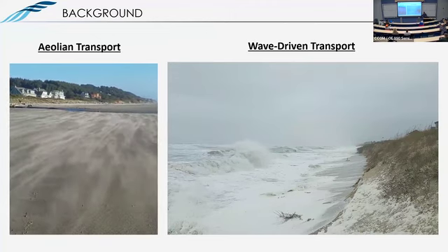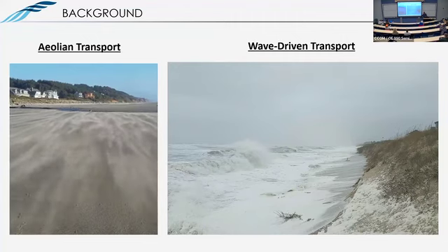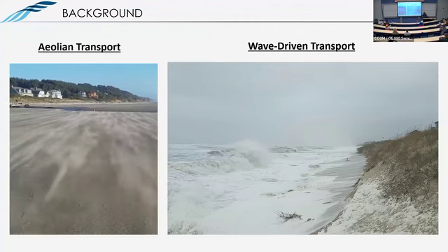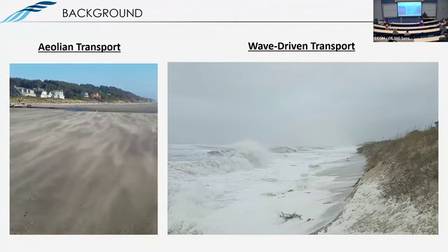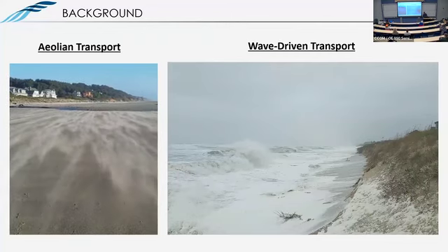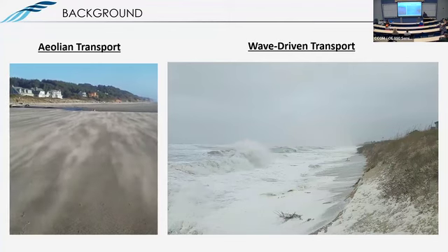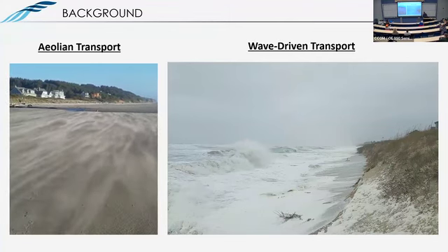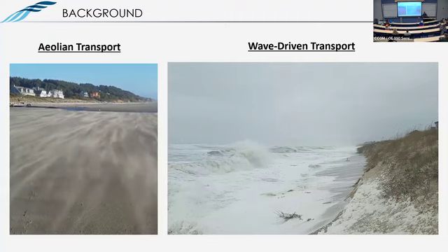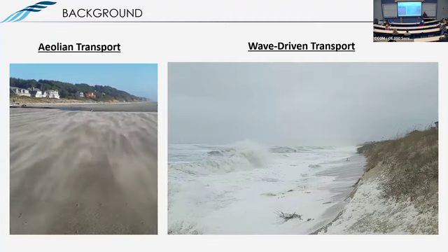And first order, imposing a large shoreline change rate, we know that's a first order effect in terms of whether those dunes are going to be stabilized, right? And so it actually motivates the point that you do need to understand the beach morphodynamics to get at what the dune resilience is. I would love to do that with process-based tools, like sediment conservation and dealing with wave physics, but the reality is over those timescales, those models break down pretty considerably and there's a huge computational cost.